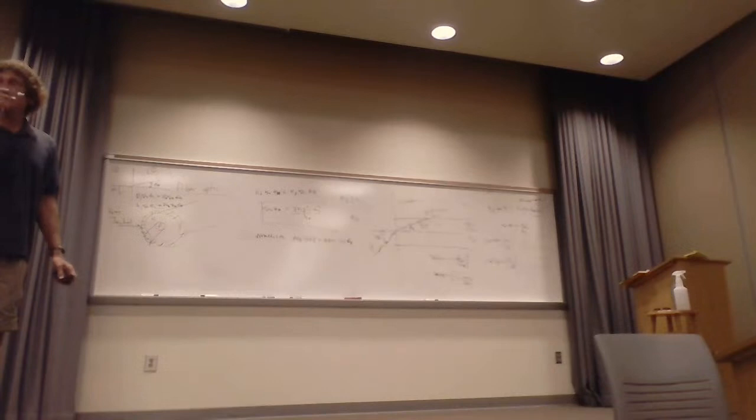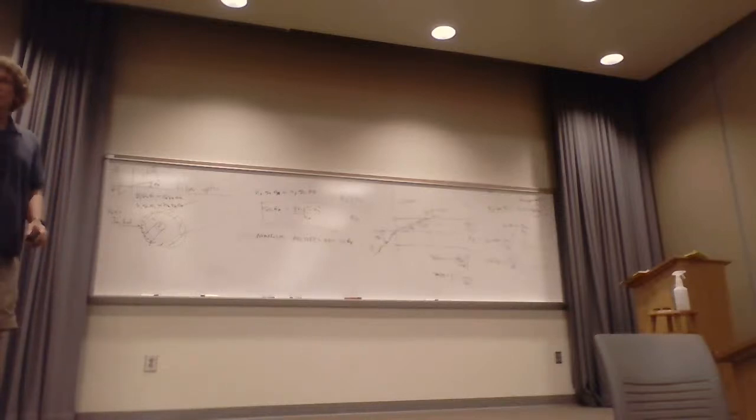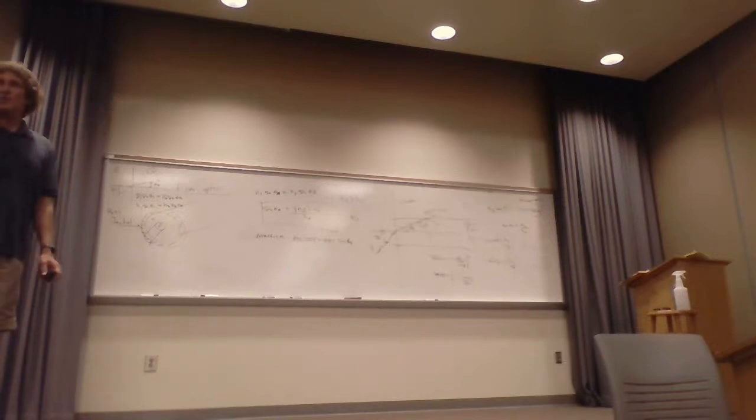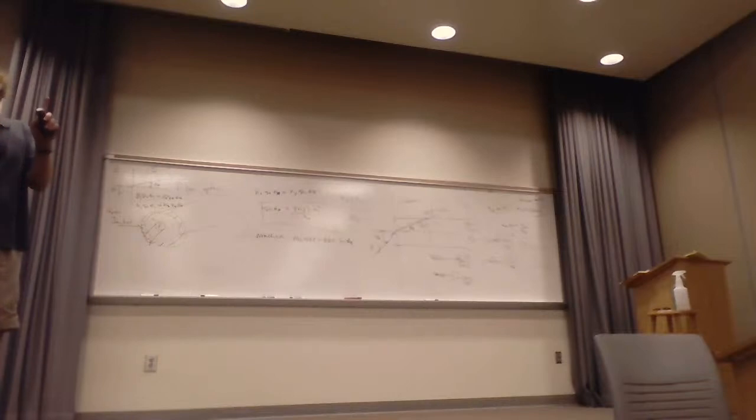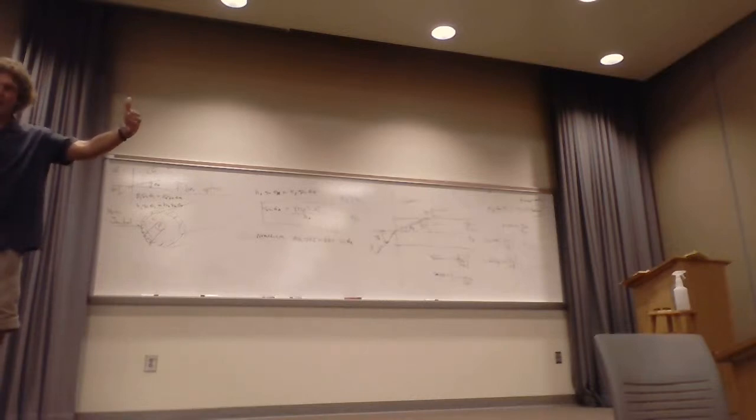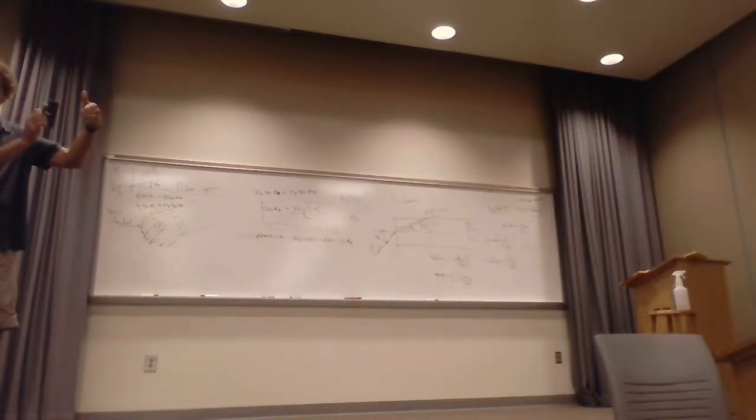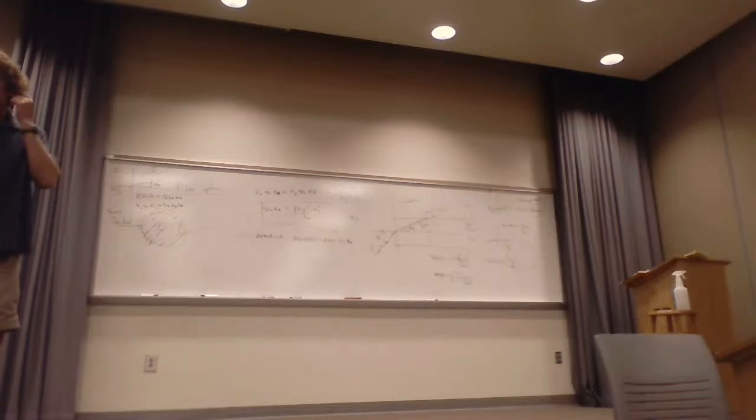Now, that's like ones and zeros. It's basically in the digital form that you want it. You don't have to decode the thing. So they go flying down, and you could think of regions of light propagating down. Think of Star Wars, where they're firing their weapons and you see a packet moving. Well, that's what happens at the speed of light on fiber optic cable, and they have photodetectors that detect this, and the pulses have to have a certain duration in order for the photodetector to detect them. And then it's basically detecting a 1, not 0, or vice versa. So all the information is sent digitally.